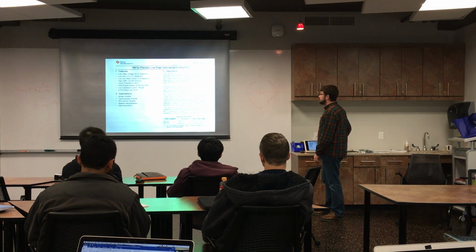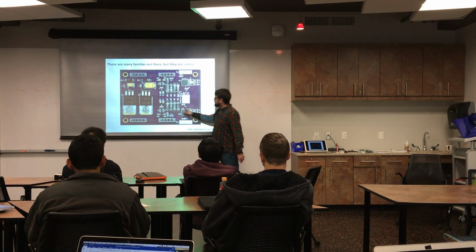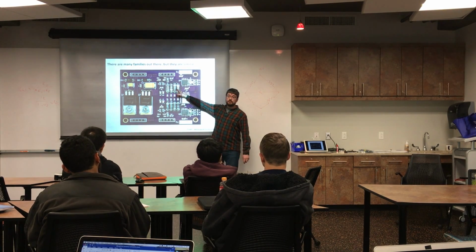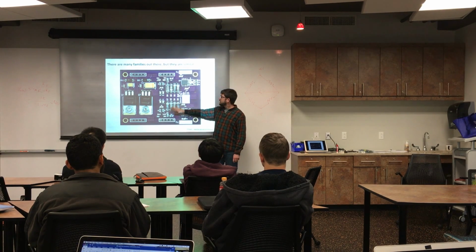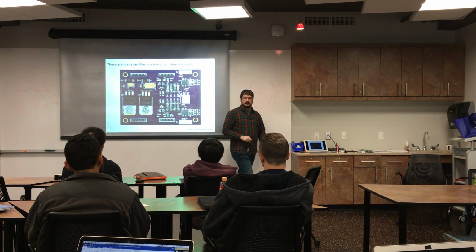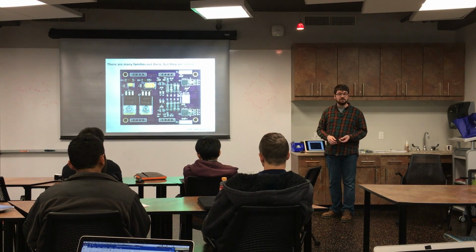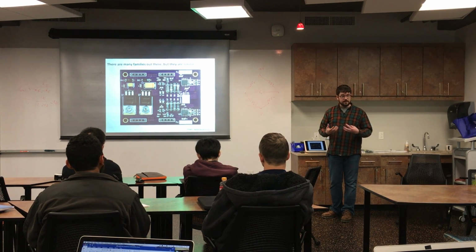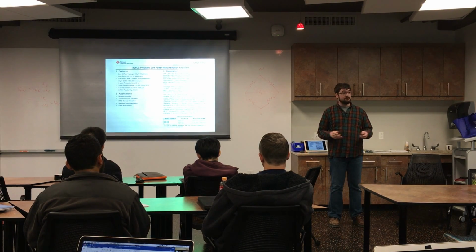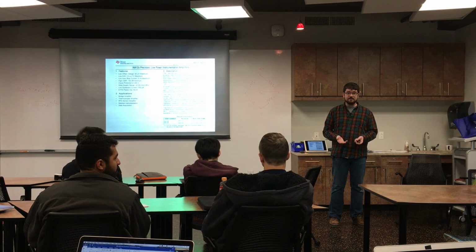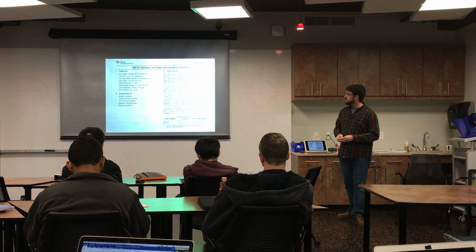And you can kind of take a belt and suspenders approach and use diodes like this to really clamp the input. Here, if you go above the supply voltage, these diodes will turn on and clamp the input to the supply voltage, and they can do that up to a couple amps before they blow up. So if it's really important that you not blow out the instrumentation amp in your circuit, say it does something like control a hydraulic press and you don't want your hand to get crushed off, you should make sure you have good overvoltage protection and out of range protection.